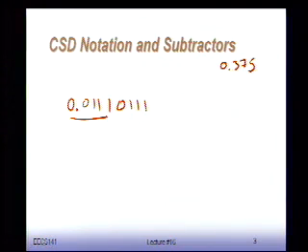Now, one way to do that is rewrite your coefficients, maybe round it off somewhere to something which is easier to use. But there's some other tricks. Actually, turns out there's a way for me to minimize the number of ones in this thing so that I never have more than 50% ones in the representation. Right now, if you forget about this thing here, I get 1/2, 1/4.